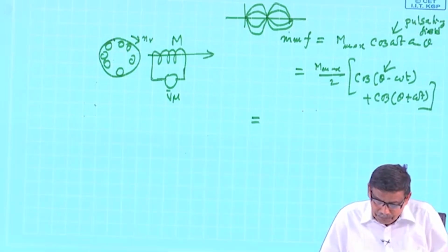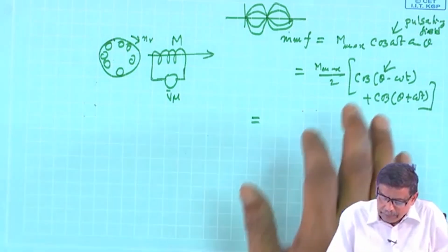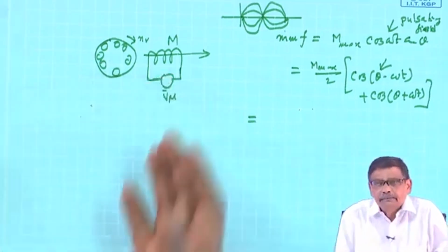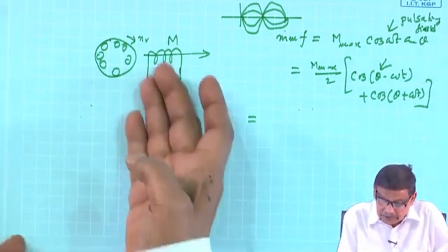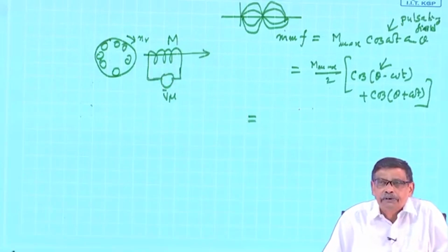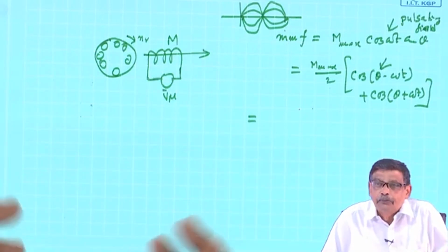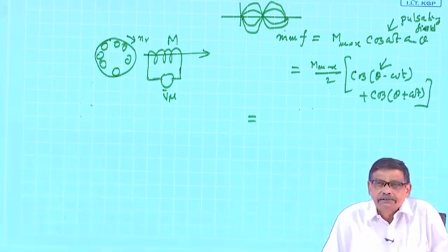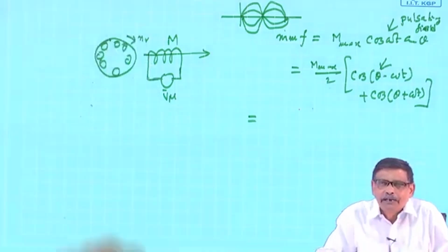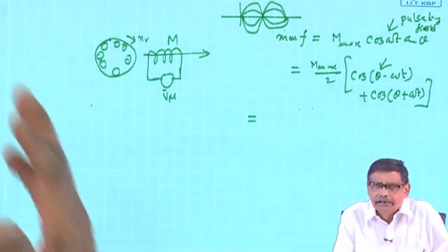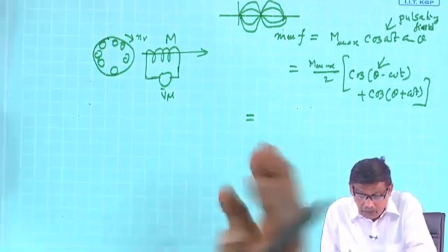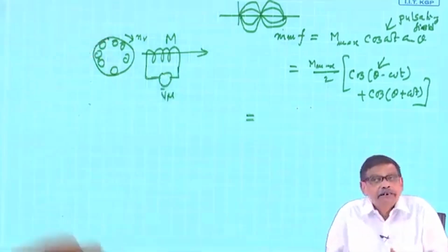Now, the question is, if that be the case, during running conditions this winding is still carrying a sinusoidal current. It will also then produce 2 rotating fields of equal strength moving in opposite directions. Then why should it produce torque? Torque will be produced somehow, we have seen very concrete evidence, but here lies the problem. Now, what really happens is, if the machine is rotating,